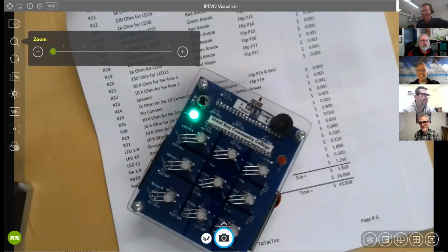And go ahead and flip it over, Ken. They can see how the Flip is mounted. And I put it on a header strip, so you can actually pull the Flip off of there, mostly for troubleshooting, so we can undo it, take it off and bench test any of the board itself. And there's a backpack on there that is the battery pack, and I put on the lithiums. That's my go-to battery now, because 2 of those puts out around 8.2 volts. So excellent battery to run any of these projects.